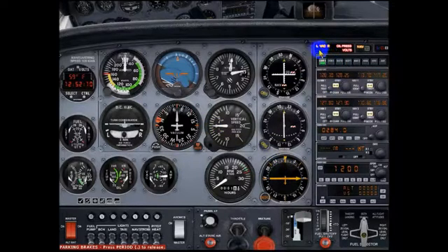One thing I did not cover, up here we have a vacuum system. Annunciator panel. The annunciator panel is lit. It lights up when it's telling the pilot, hey, our left and right vacuum system is out. There's no oil pressure. We're having a problem with voltage, meaning that electricity is being drawn, but the electrical system's out of whack.